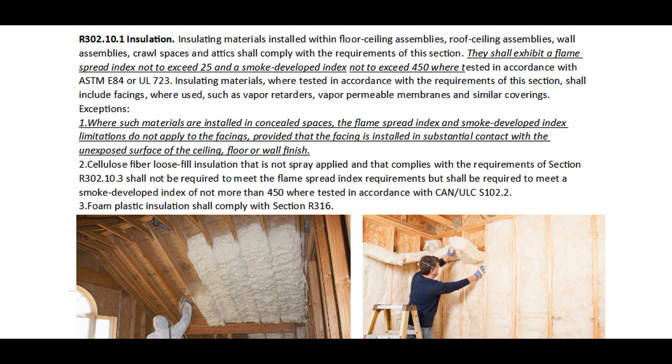2. Cellulose fiber loose fill insulation that is not spray applied and that complies with the requirements of section R302.10.3 shall not be required to meet the flame spread index requirements, but shall be required to meet a smoke developed index of not more than 450, where tested in accordance with CAN/ULC S102.2. 3. Foam plastic insulation shall comply with section R316.